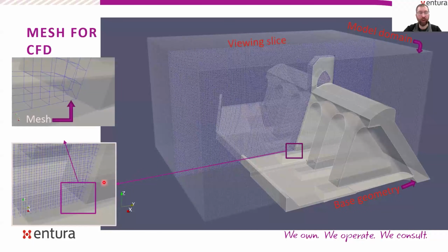And when we look at the detail of that mesh on the left-hand side, at a particular part of that mesh in the top left, you can see that the shapes we try to make, the volumes, these computational mesh elements, are cubic by nature, and sometimes distorted cubes as they try to fit to the shape of the structure as part of that meshing process. So the meshing system that OpenFOAM uses is kind of a bunch of cubes like Lego, and then they are fitted to structures, snapped onto the structure to give it more detail where you might be interested.